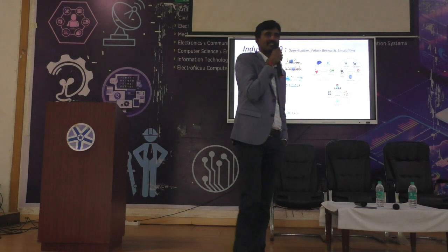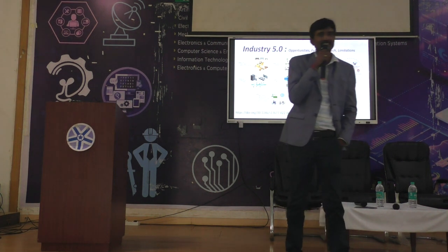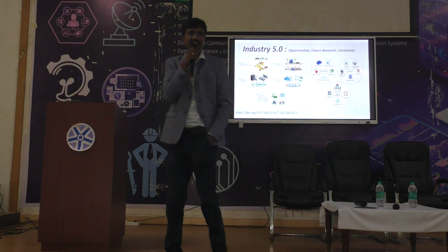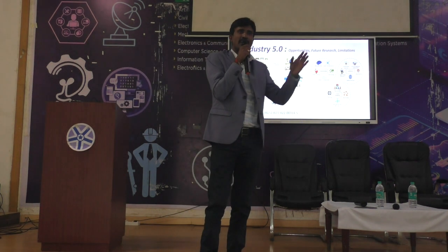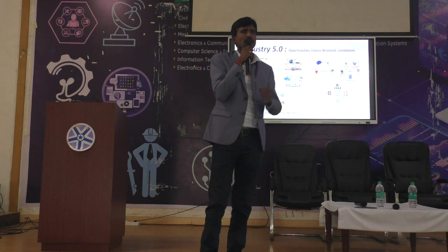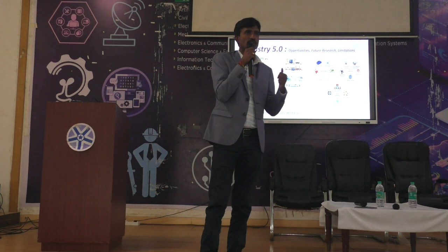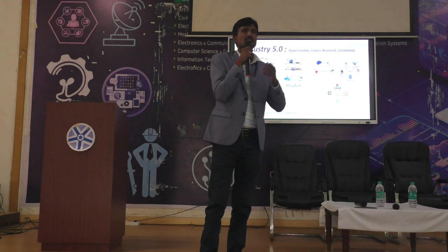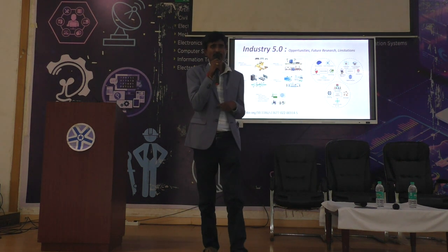Grease is a semi-solid lubricant. Yes? Graphite, okay. Graphite powders, yes, good. And calcium fluoride, CaF2. And we can also use polymers. But the main problem with polymers is they are going to degrade at high temperatures. Because in these cutting tool applications, polymers used as a solid lubricant are not going to sustain at those high temperatures. So we can't use them. Yes, we can use graphite.